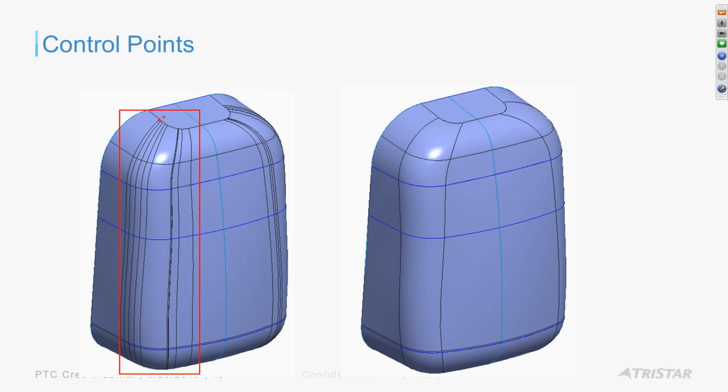Yes, I could add control points, right? I could add a few control points here and say I want you to just use that. Many times it's just a matter of using the software's automation tools, where you say, I want you to map arc to arc automatically if available. If you try it, you'll see by default you don't have to spend a lot of time adding these control points. You can, of course, change the control curves manually if you'd like by adding additional points, but by default, you can at least get a good continuous surface there.